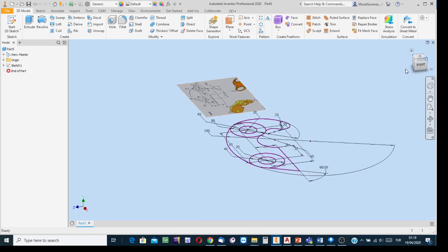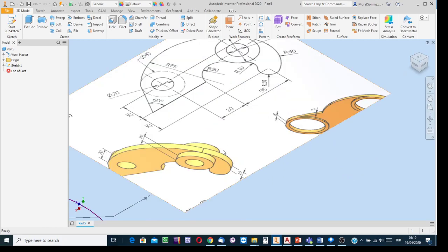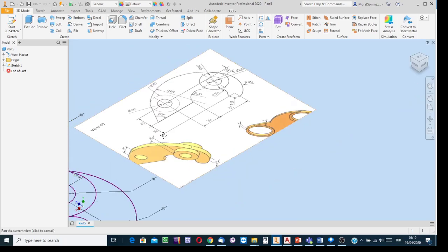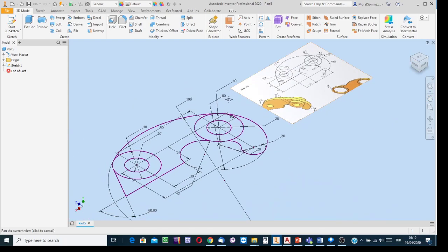Well, here, have a look at this pictorial figure. The thickness of the main part is 10. Okay, here there is a boss, its thickness is 10. I know that the other boss is also the same thickness, 10. The thickness of this part is 20. 20 minus 10, this means the length of the other boss is 10. Okay, knowing such values, apply the extrusion process.